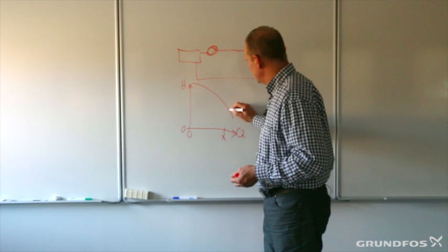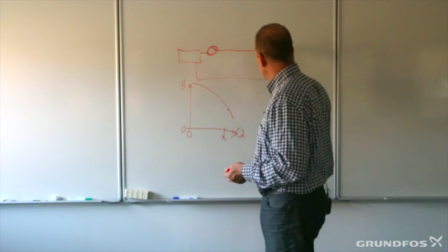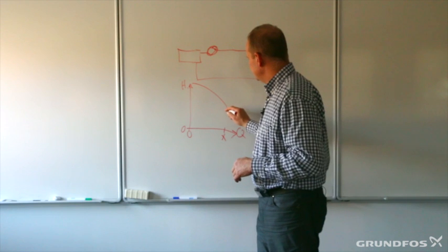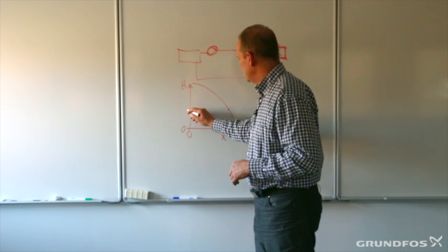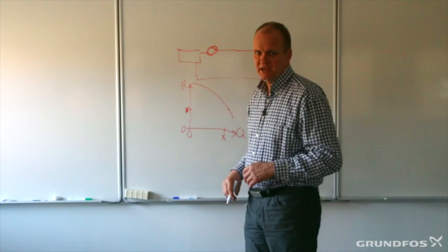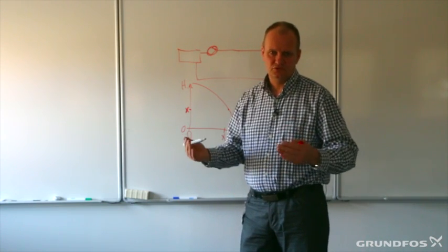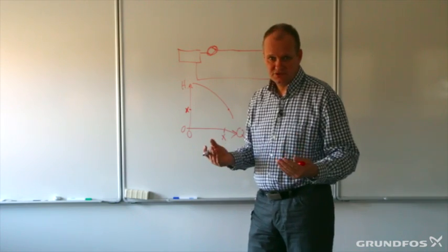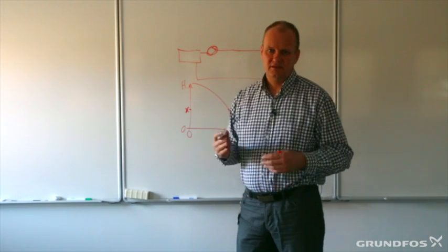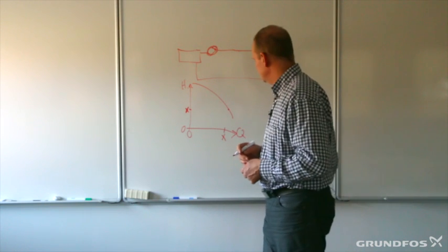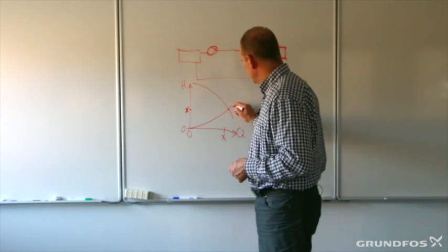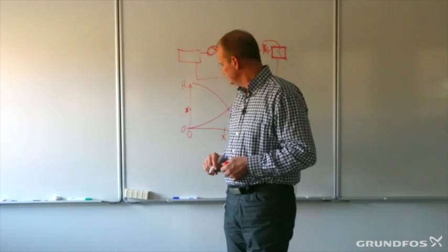And then we calculate what is the pressure loss in our system here. The pressure loss will then tell us how much pressure this pump actually needs to be able to deliver to the system in order to make it flow in the right way as we want it to be. So when we have this point out here, we could draw what we call a system characteristic.